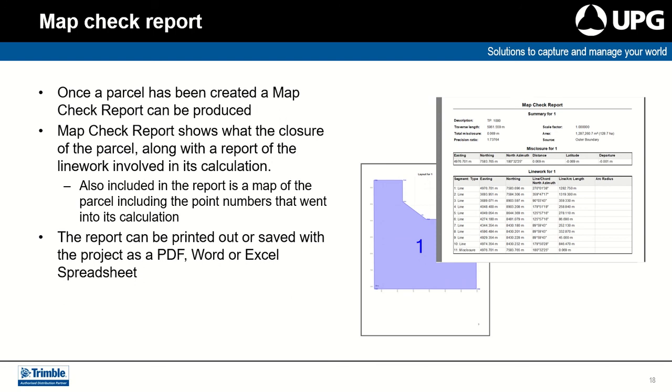When you're going along and creating your COGO, there are things that you can do after it's been generated, such as macros that are available to allow you to define an area, and it will split up your specific lot into smaller lots based on an area size. So there are some macros available that can create parcel boundaries automatically to assist you further in this process once you've generated these things.